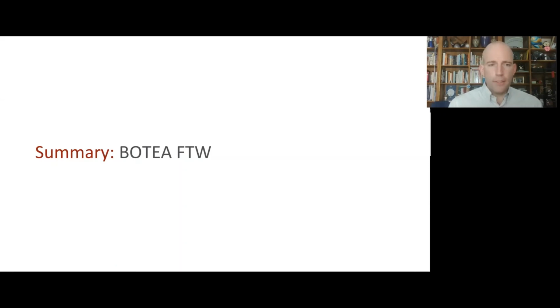If we bring all those things together, we can usually find a simple symbolic approximation of the energy loss due to, say, sliding friction, a very common energy loss in our systems. Then we use that, along with an analysis of the energy we care about, to see not only whether that sliding loss is big for the candidate system I'm looking at now, but what terms I should adjust in order to make it smaller and reduce the energy loss in the system.